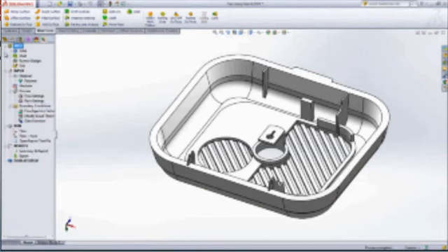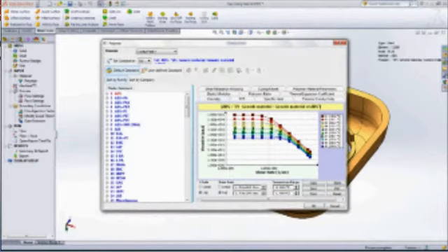Once the mesh is created, we can go forward with setting up the rest of the boundary conditions. The next thing to do is to select the plastic material. Mold designers can simulate the molding process very accurately thanks to the Solidworks plastic database that includes over 4,000 grades of commercial plastic materials. For this initial analysis, we choose a grade of polycarbonate.